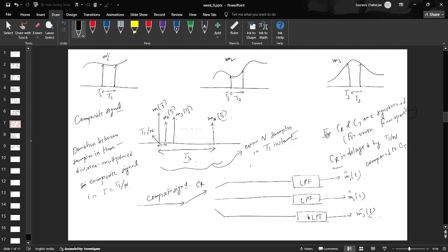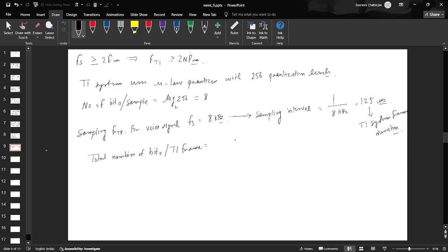I mentioned that there is one pulse which doesn't carry any useful information from the data perspective, but for synchronization it is very useful because it is used for the synchronization task between the commutator on the transmitter and receiver side, which is essential for error free operation. So actually in each frame you transmit 24 message samples plus one synchronization pulse.